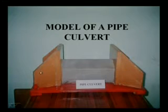Sometimes in the place of wing walls we also have slopes. In a similar way we can substitute the wing wall with a slope. That means we provide slopes here filled with granular material, and these are overlain by a thin layer of stone masonry. Just have a look at the next slide.